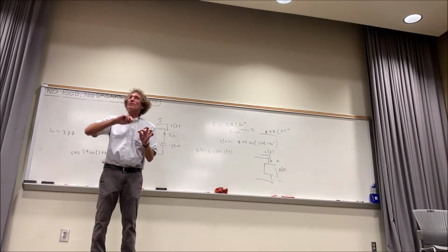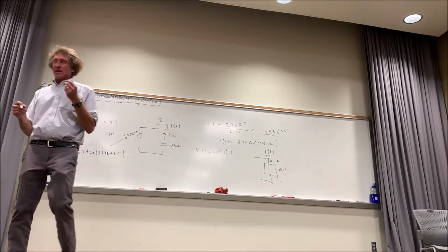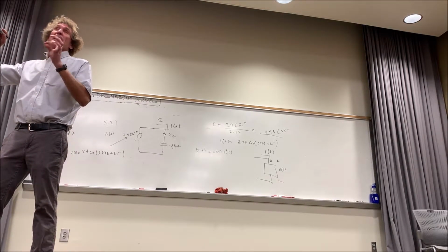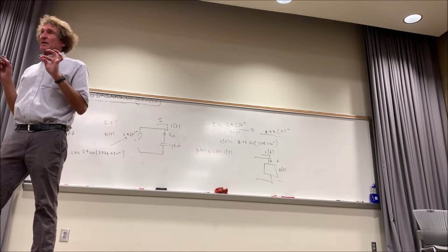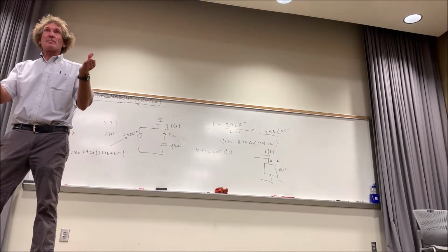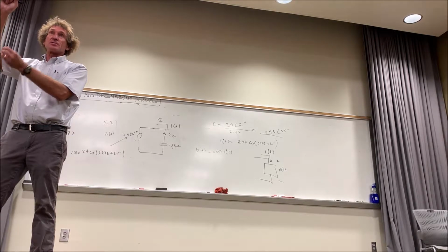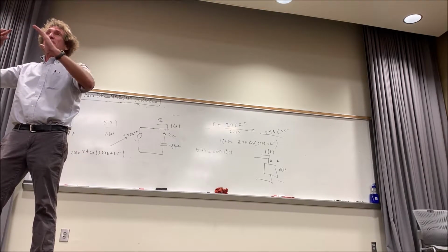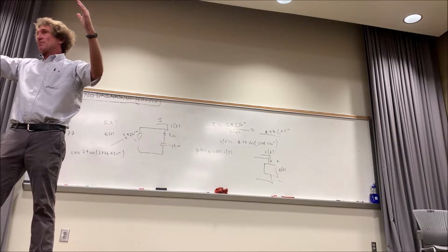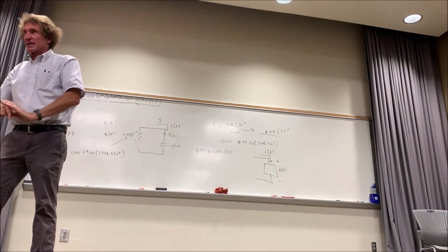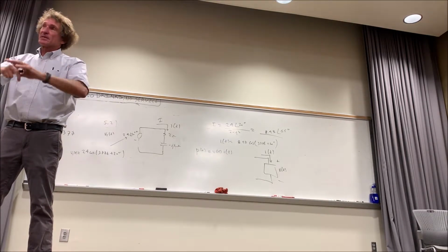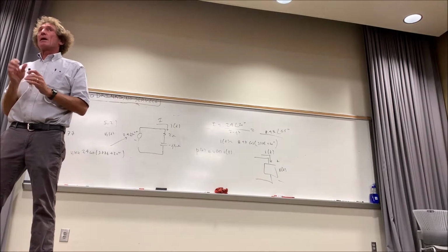And by the way, over a cycle for either an inductor or a capacitor, at times you will be supplying power, and at times you will be actually taking power out, or negative, or dissipating power. And here's why: over one cycle, current's going to flow in a capacitor, charge is going to accumulate in the plates, a voltage is developed, an electric field is around there, electrostatic energy is left inside or in the area of that capacitor. Now, as the waveform starts going through the second part of the cycle, all that energy is dumped back into the circuit. So the net effect for a capacitor or inductor is it gets energy, then takes the energy and puts it back in the circuit. And the net amount of dissipation is zero.